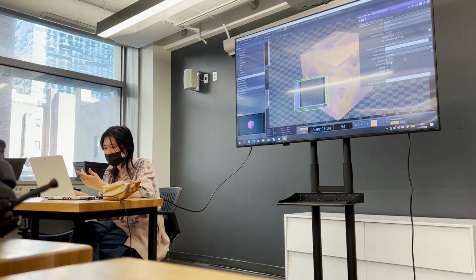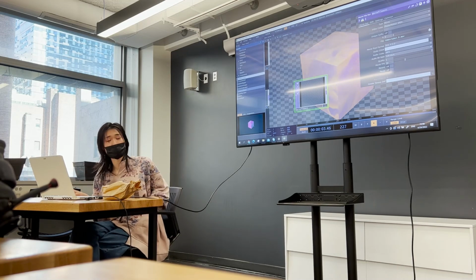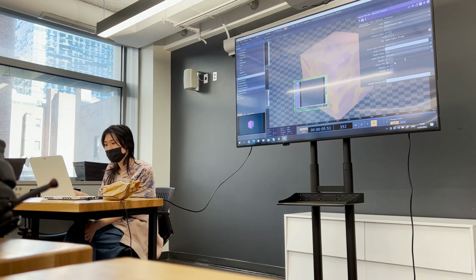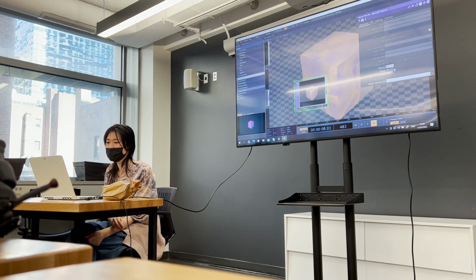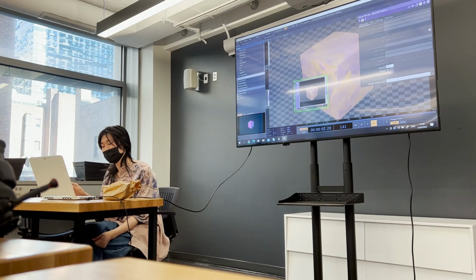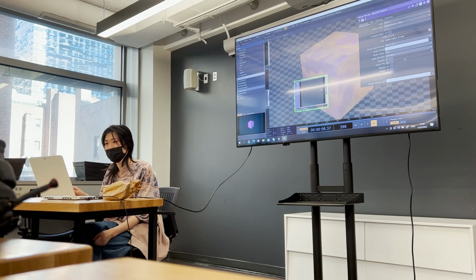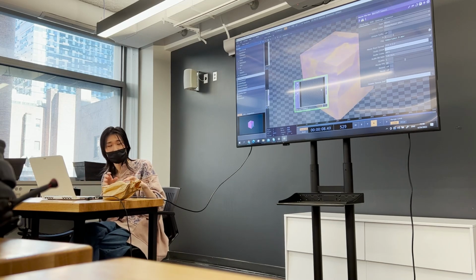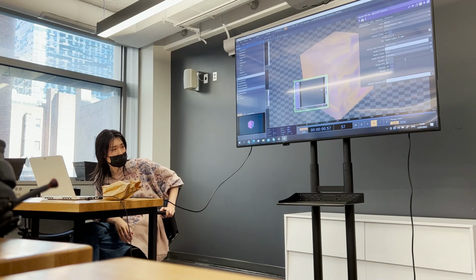You can change to 60 if you want, because by default, TouchDesigner works at 60 FPS. Just turn on record. You might drop frames, and you just wait until you're done. Click off, and then it's probably saved to the same folder that your TouchDesigner file is in.